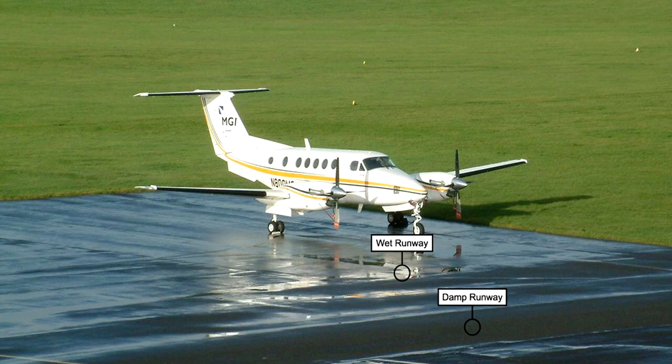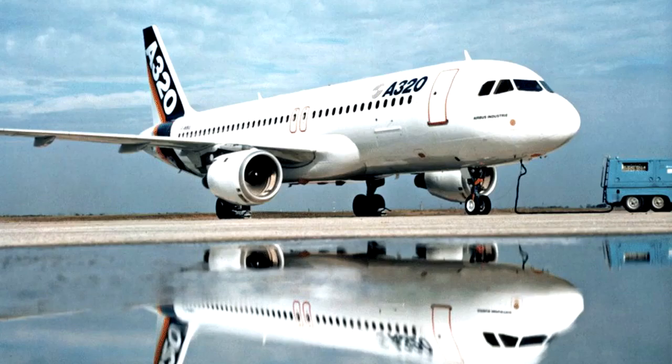A wet runway is one whose moisture level makes the runway appear reflective, but there are no areas of standing water in excess of 3 millimeters deep. A contaminated runway is one when there is more than 25% of the runway covered in a layer of moisture whose specific gravity is equivalent to a depth of 3 millimeters or more of water.